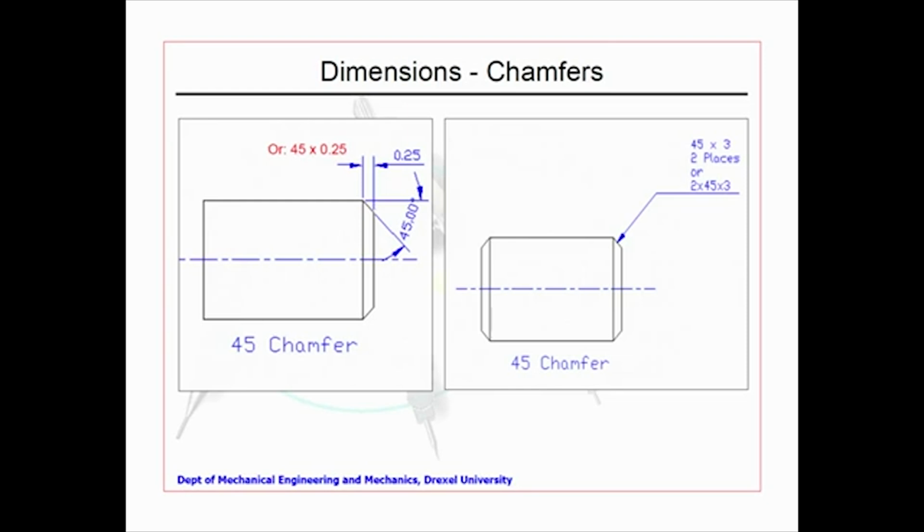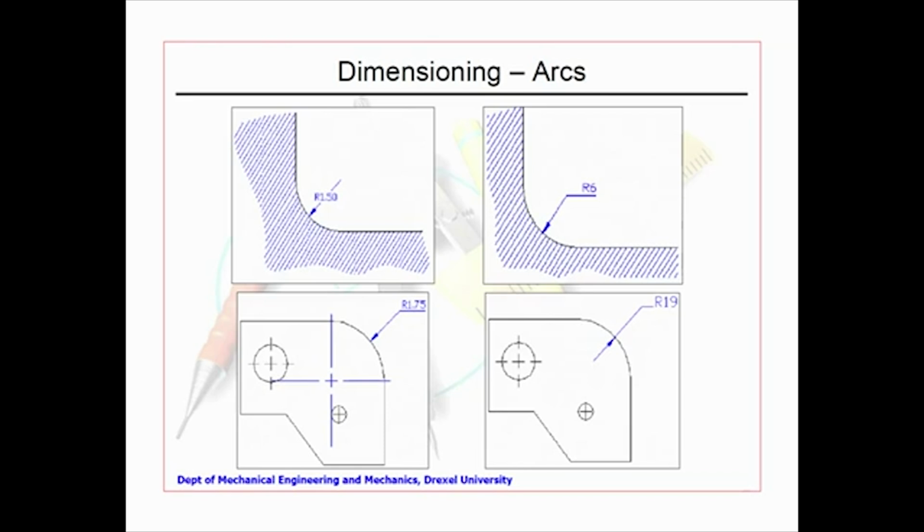it clearly says 45° chamfer, 45 into 3 at 2 places, 45 at this. This is a convention which is followed. Fortunately for us, that is those of us who are moving out to the new CAD and we make a solid model, probably even if you were to miss, the drawing can be read and the process people will be able to understand those things.